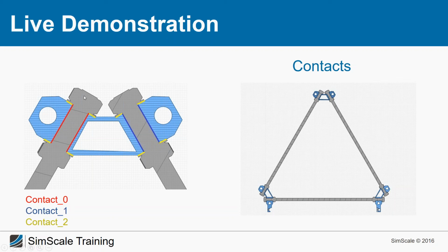And therefore, I decided to fuse these parts, because that will reduce the number of contacts we have to define. Right now, we have 9 contacts. If we would not fuse it, we would have maybe more than 50 contacts in the end. And that's a question you have to face every time. So, there's a general rule: as many contacts as really necessary and as few as possible. But I think you knew this rule from other things.